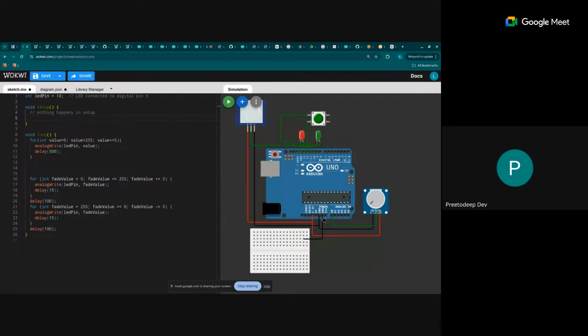Okay, got it. So this breadboard will act like one more ground. I am connecting this directly, right? But physically, if you are using jumper wires, you will only be able to put one jumper wire there, right? Correct. Just one pin will fit into that. That's why, if you are connecting multiple components, you use the breadboard and connect a ground pin. If there are many components there, you might want another ground pin for that. Makes sense. Got it. Thanks.